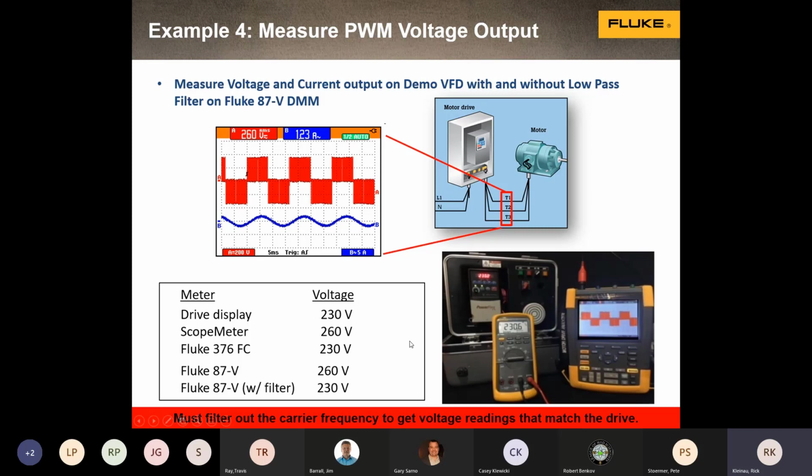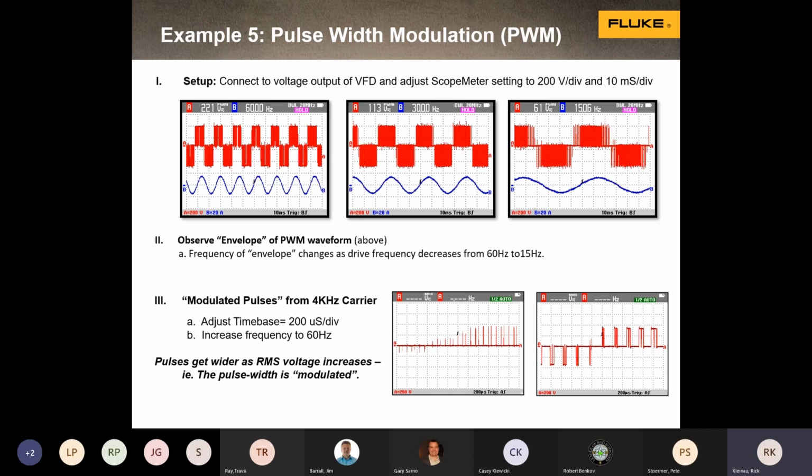We have, I don't know, half a dozen tools. Actually, the scope meter, I could put it in what's called the VPWM, for pulse width modulation, mode and get a number that matches the drive. Well, you saw this display without the amperage. Here, these readings across, these three images on the top.